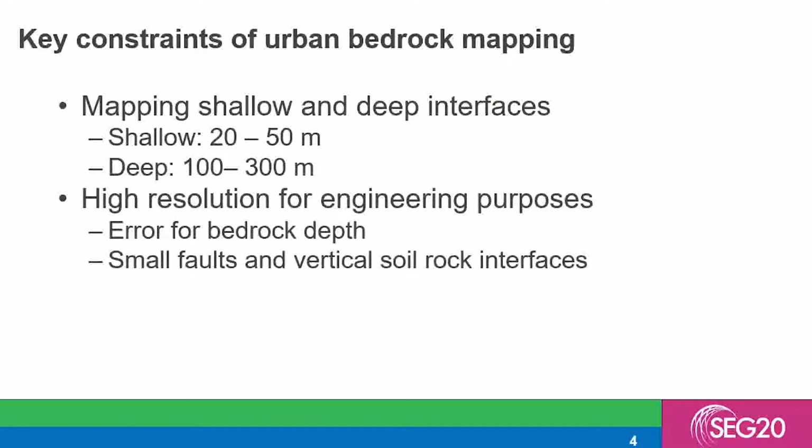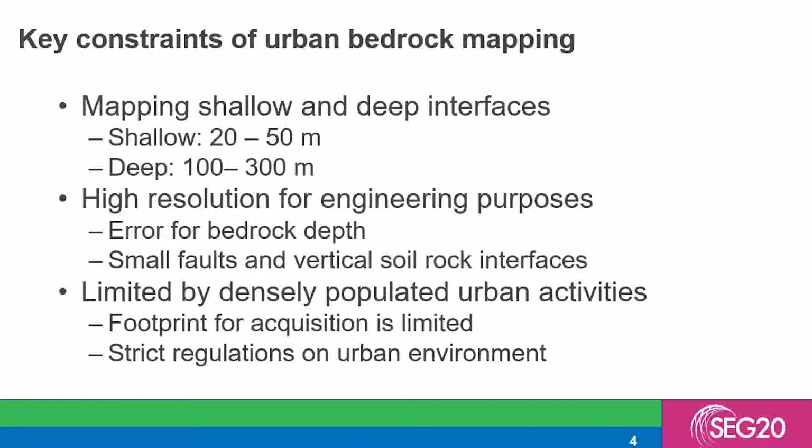Besides that, the resolution should be really high for these purposes, and the errors that can be tolerated by civil engineers are really small. Besides, as Singapore is a very populated area and we don't have much space for observation, how to conduct an acquisition in that already built, limited area is a big problem. The acquisition is limited, the survey line cannot be too big, and we are also restricted from using any exclusive method. So how to get this high resolution bedrock map is a big problem.